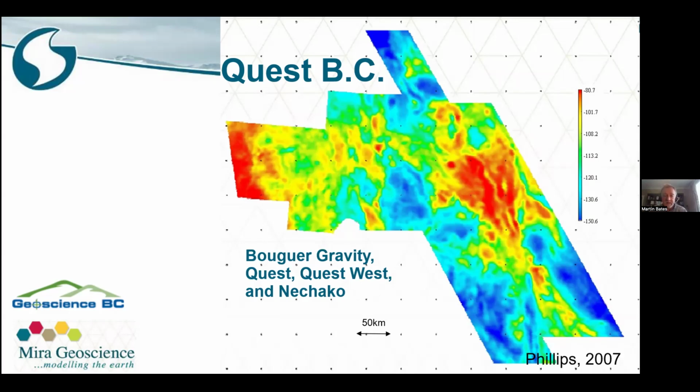Nice maps. So this is a gravity survey, and we flew in British Columbia in the mountains. So lots of topographic effect, because obviously you have to correct: the density is not just rock type, but also is there any rock there at all? If there's a mountain, that's going to cause a gravity high. Well, the mountain's there, so you can correct for that.